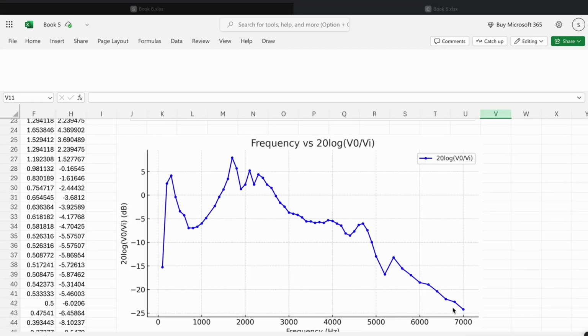The most prominent peak in the FFT graph is at 1.3 kHz, which is likely the resonance frequency of the piezoelectric sensor. At this frequency, we know that the piezoelectric material is responding strongly. The strong peak at 1.3 kHz suggests that this is a resonant frequency of the piezoelectric material. This graph helps to identify the frequency response of the piezoelectric system, useful for vibrational analysis, ultrasonic applications, or stress sensing.